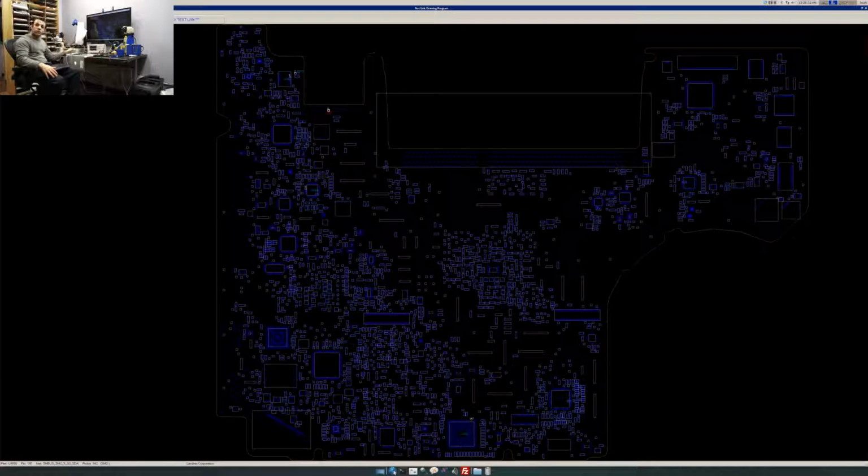I figured if I inject 3 volts into that line, whatever is pulling it to ground is going to get very, very hot. And I was dead wrong, because the short, while being a short, was not enough of a short to actually pull more than 0.1 amps. Good luck feeling a short when it's 3 volts at 0.1 amps. Nothing's going to get hot.